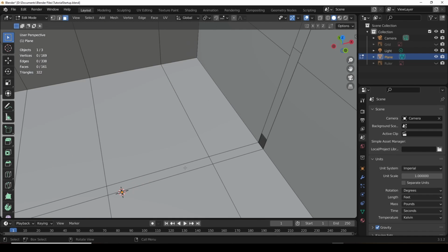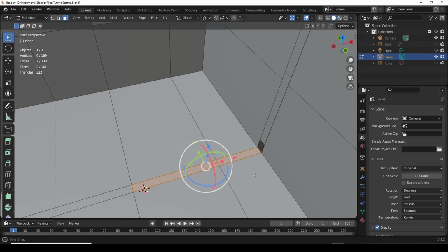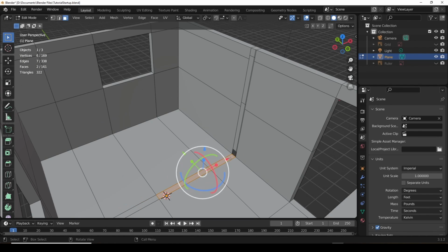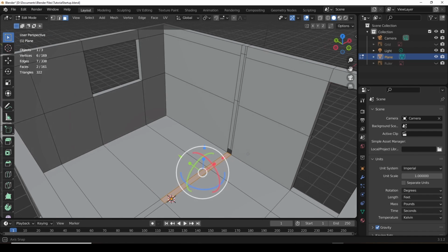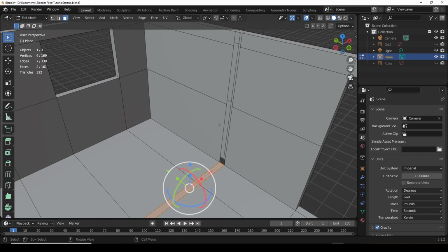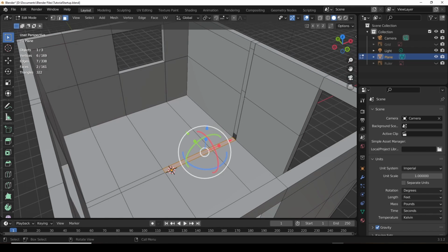So I'm going to hit the C key, select that and select that, and I want to extrude these up. Now, since we want to match these to these faces, we're going to use a very nice feature that allows us to extrude, and at each step snap to these lines and then extrude again and snap to these lines, so that we're matching the geometry.